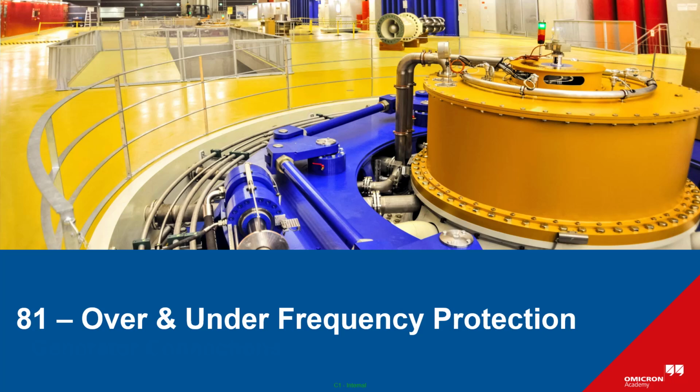In this video we will be focusing on the frequency protection, specifically the 81 over frequency and under frequency protection function and how they work together with voltage related protection. Frequency deviations can stress both generators and turbines, causing mechanical stress, overexcitation or even system instability. We will explore the operation of this protection, their typical setting and how to test and verify them using the OMICRON Test Universe modules. You will see how under and over frequency stages as well as related voltage tests are tested step by step to ensure the relay responds correctly and reliably. So let's dive in and get started.